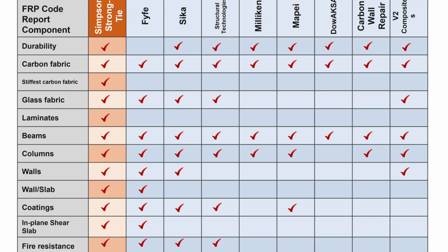So what we tested for stiffness is basically tensile testing, where you make a witness panel, cut little coupons out, and then pull it. It's not really something that's in, I mean, it is in the code report, but every manufacturer has a stiffness in their code report. And every other manufacturer's stiffness in their code report is lower than ours.